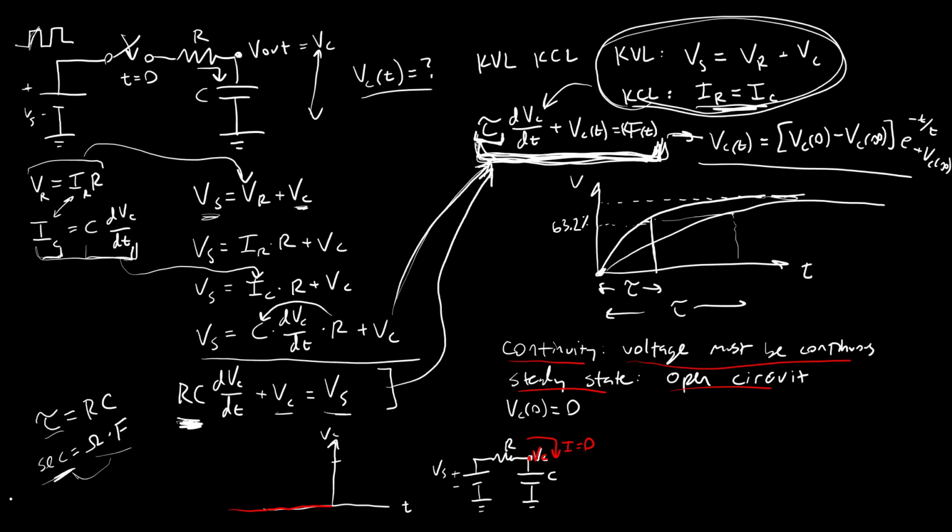And this is something that actually trips a lot of students up. I asked this question in a previous video with an open switch instead of a capacitor, but again, if it's an open circuit, same concept. A lot of students will look at that and say, oh, there's no current, and you think of Ohm's law, V equals IR. Well, if there's no current, then there's no voltage, so the voltage must be 0. And that is sort of a misapplication or misunderstanding of Ohm's law.